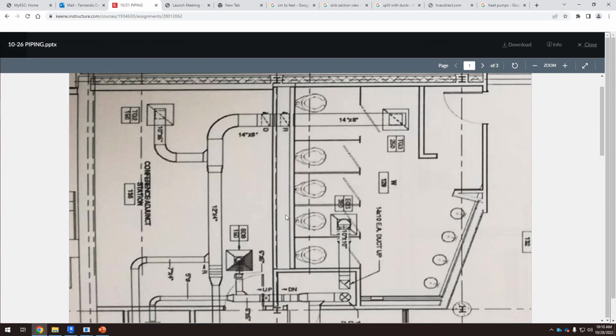And when we have a horizontal element for the drainage system, this horizontal element needs a slope. Okay, so it can't be flat or horizontal. So we need a slope. And at the same time, that's the drawing. Not only do we need a pipe going down to get rid of all this, but we need another pipe going up, the vent, because we need air inlet, because the air is what makes it go down.